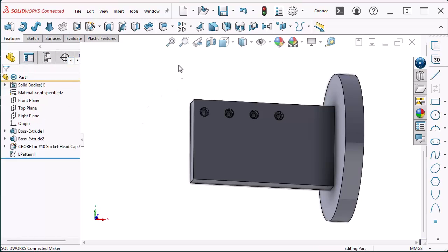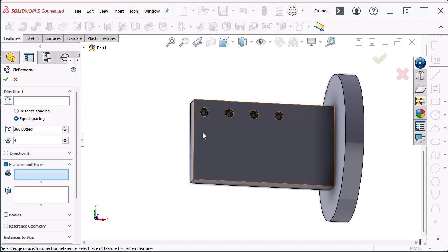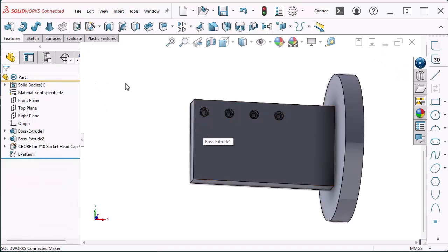If we were to make a circular pattern, the first thing we would have to have in SolidWorks is some sort of a center. And this is where the Solid Edge method has the advantage, because you can sketch in a circle here, give it dimensions, and go on your way. But SolidWorks expects you to have something done beforehand.